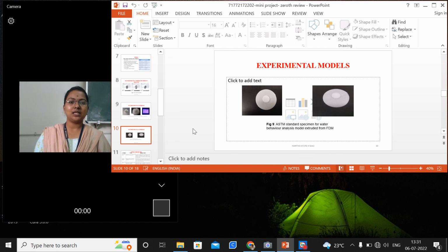We take the initial weight of a material, and then the final weight after it is immersed in water at 37 degrees Celsius. At that point it can be evaluated with respect to time, in hours, days, weeks or months. After that we weigh the material to see how much the percentage varies with respect to the weight in grams.